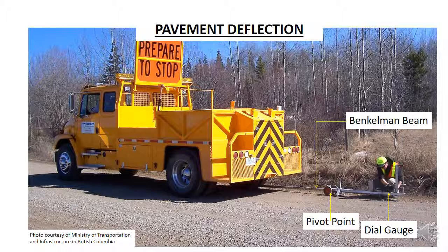This test gives you a pretty good idea of how well the road responds. If the rebound is too much, then the road is not properly compacted, or it is coming to the end of its life.